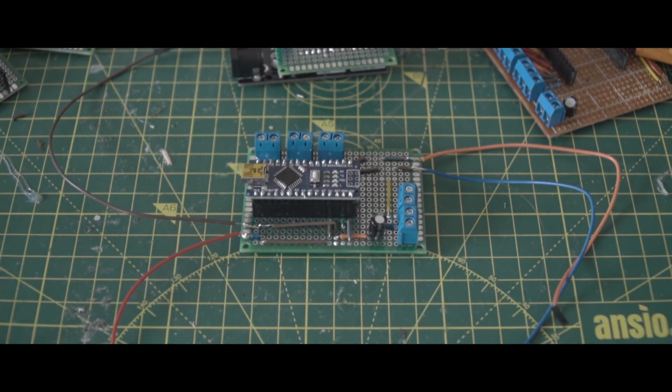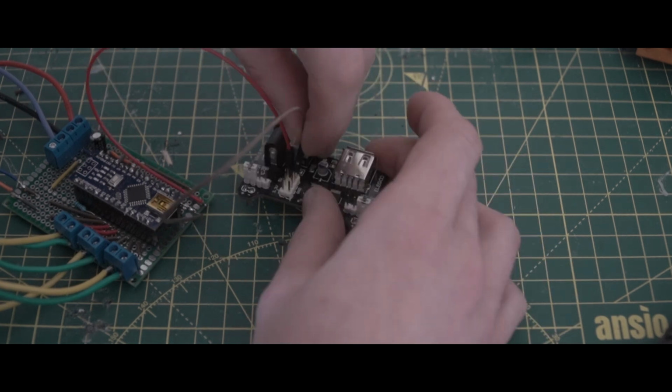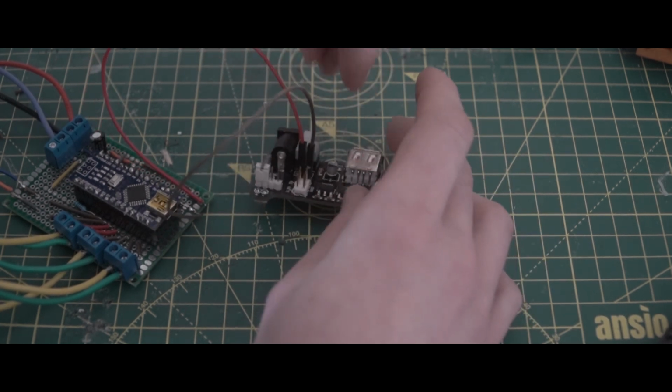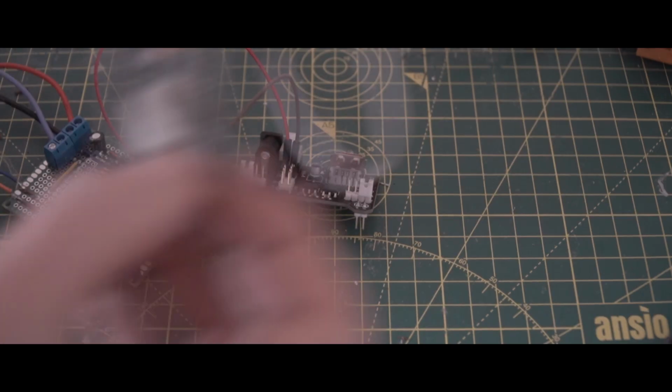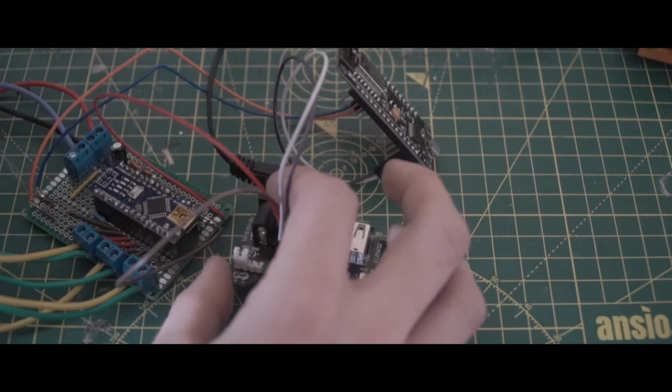The Arduino is receiving 5V power through the voltage in pin from a small power supply, with the ground returning to the same power supply. It's important to note here that when connected, the Arduino and Node MCU must share a common ground in order for the timing of the serial messages between the two boards to remain consistent. This is one reason for using an external power supply rather than powering everything from the Arduino's internal 5V rail. It also allows me to power both microcontrollers from a single 9V DC main supply.